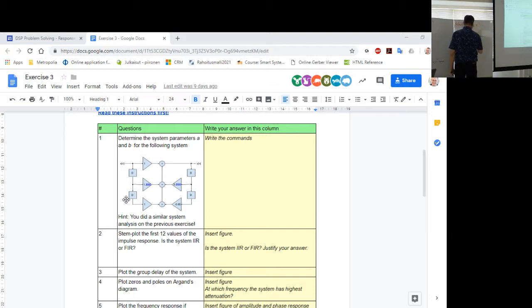And then you basically just check the impulse response. This is an nth order system, meaning what is the highest polynomial number, meaning how many terms you have, minus 1. And if the order number is n, then the impulse response either stops here or continues. If it continues, then it's IIR. If it stops, then it's FIR.